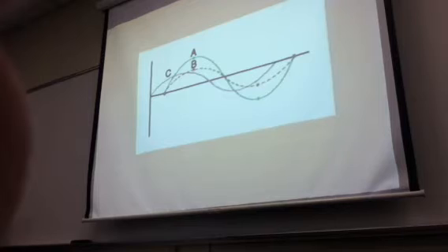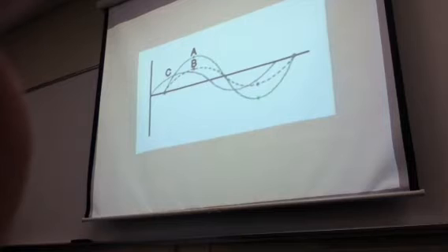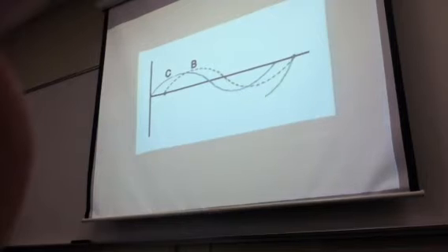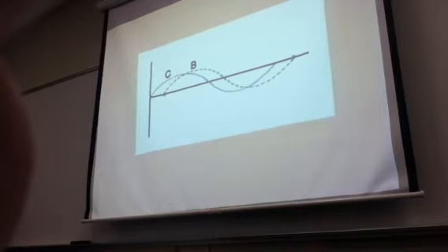Comparing the waveforms of the previous example on the same axis, waveform A represents the voltage applied to both circuits, and waveforms B and C represent current flow through the resistive and capacitive loads respectively. Now, let's remove the voltage waveform. It's obvious that current in the capacitive circuit is leading the current in the resistive circuit. Let's see how this principle is used to help start induction motors.